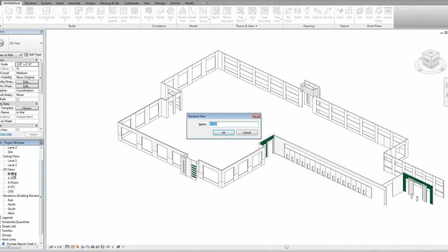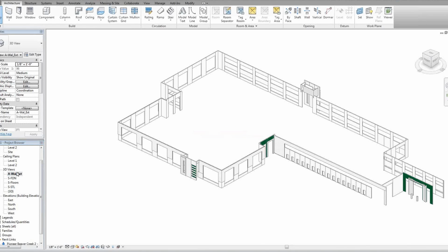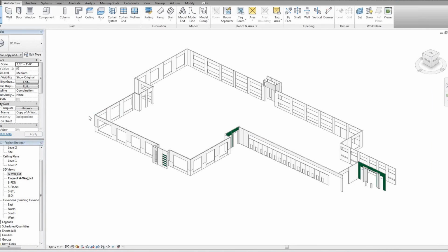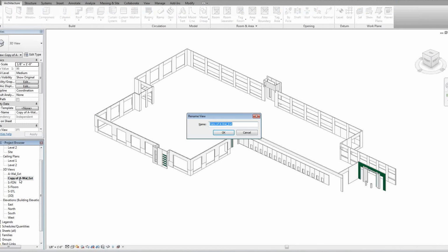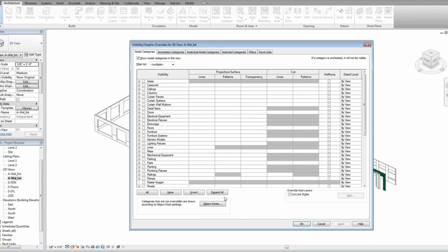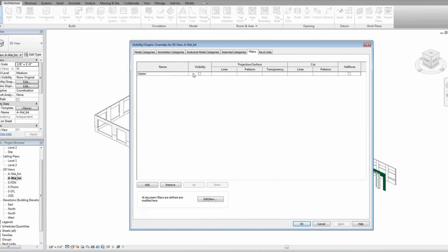So this A-wall really is exterior architectural walls. So we can then make a separate export if we want for interior walls. So I duplicated it. I type F2, A-wall underscore INT for example. So basically, I'm just going to be reversing that filter. So right now it's saying turn off anything that has an interior visibility. So I want to turn off anything that has an exterior visibility.